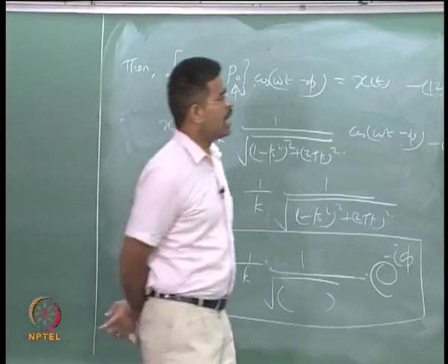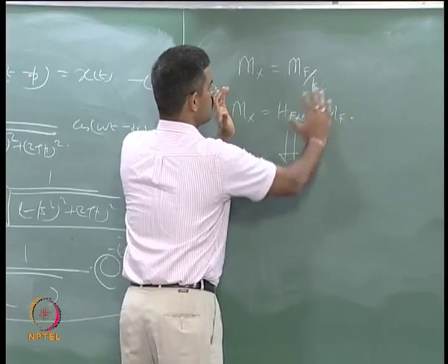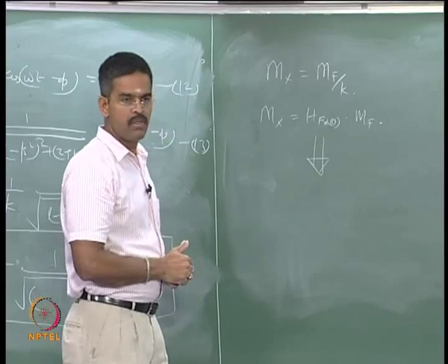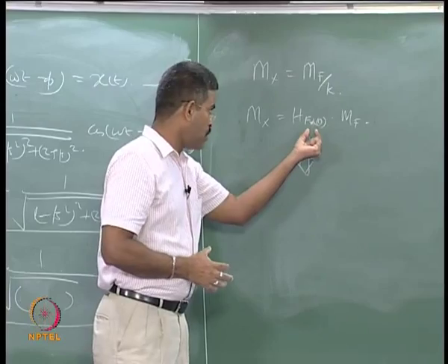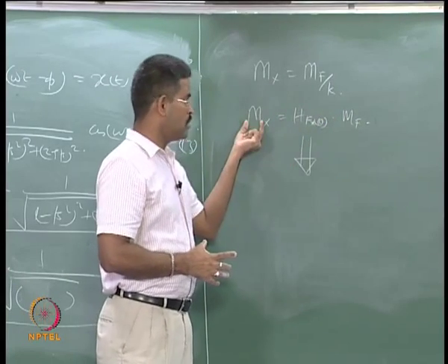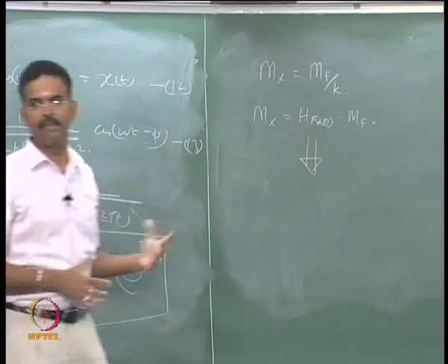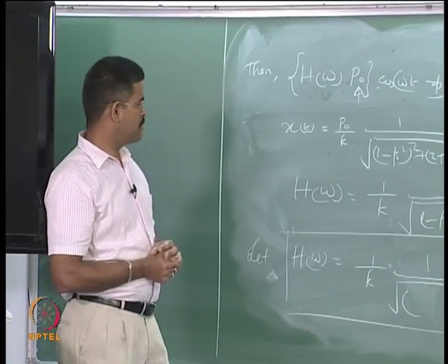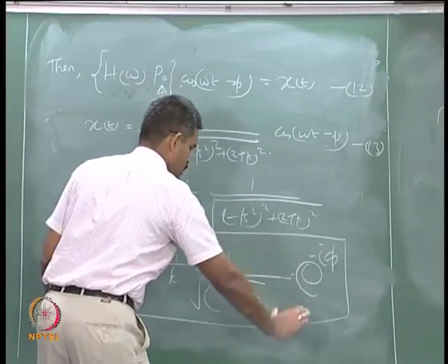Okay. So, it amounts to a very simple expression. If I have the mean of the forcing function which is a stationary process, which is true for wave loading, I can easily find the realization of the response of the system from the load using the transfer function, which is independent of time. Okay. There is no time domain, there is no time component here at all, is it not?